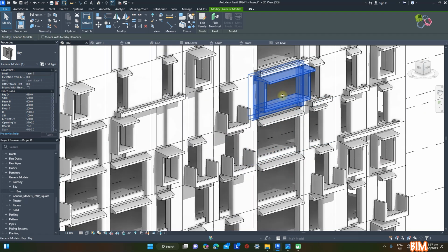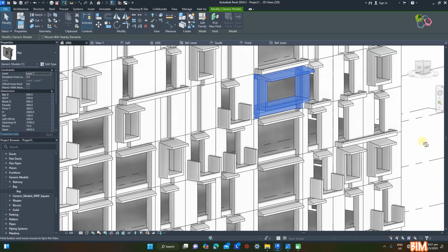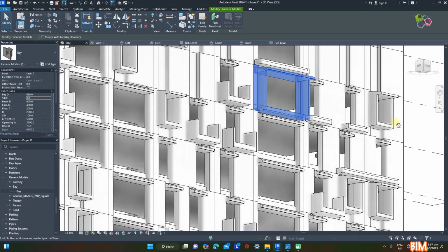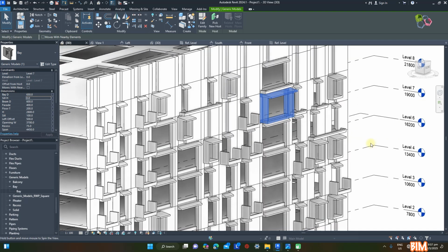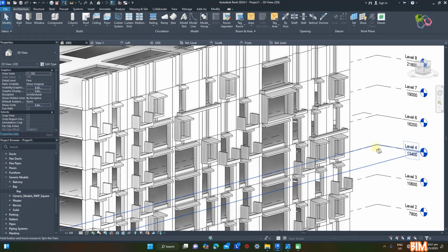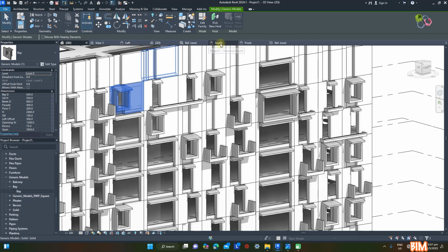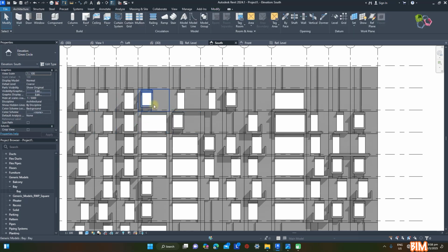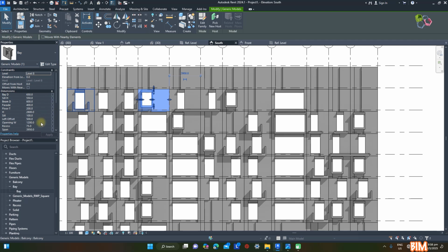Go to south elevation. This panel is installed on the living room, so the opening will be a full height panel. Sill H, height, parameter must be 0. Perfect. Let's rotate the view. This panel is on the living room as well. Let's check the panel below. It's 3200 mm shown in the Properties palette. Select the above panel, the opening width is supplied with 3200. This bay panel has 200 mm walls on both sides, so we need to reduce the opening width.